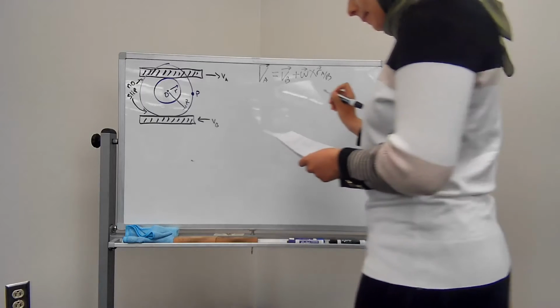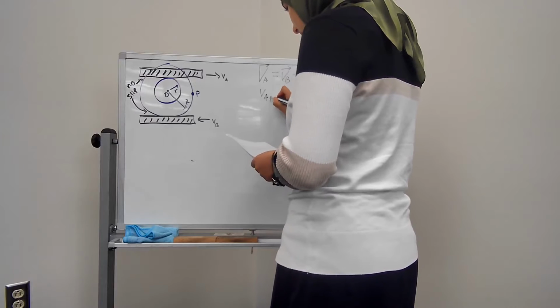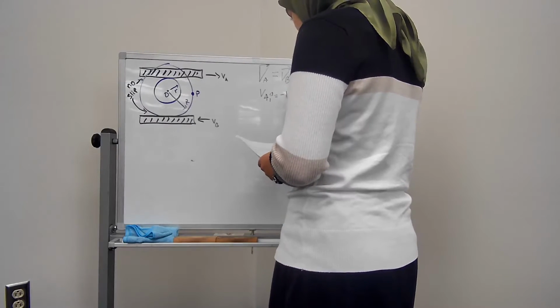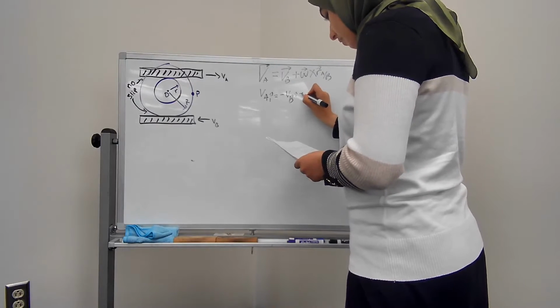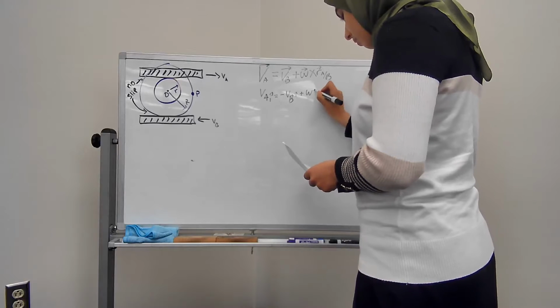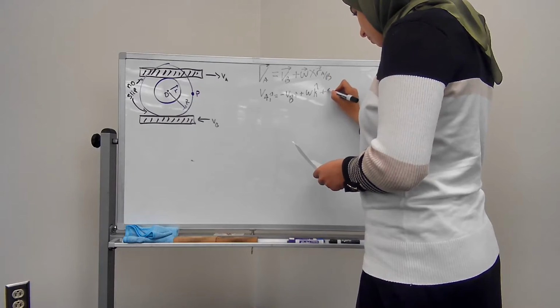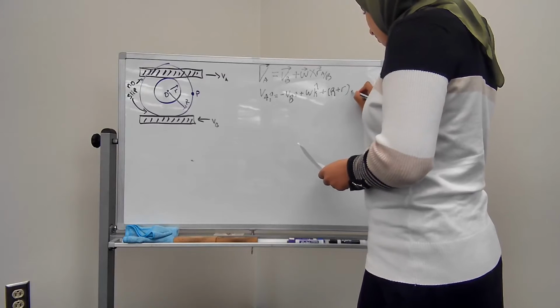And we can do that by using the equation that we've got from chapter 2A for velocity. That equation is V of A equals V of B plus omega cross R of A slash B. As you work through this, your omega equation will come out to the negative value of V of A minus V of B, all divided by big R plus little r.